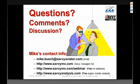All right, then we had a couple other questions coming in about determining horsepower while in flight. Determining horsepower. Yeah. Well, again, there are two modes to operate an engine: rich of peak and lean of peak. When you're operating lean of peak, which is the way I normally operate my engine in all phases of flight other than takeoff and climb, computing horsepower is extremely simple. You take fuel flow and you multiply it by a fudge factor, and you get horsepower.